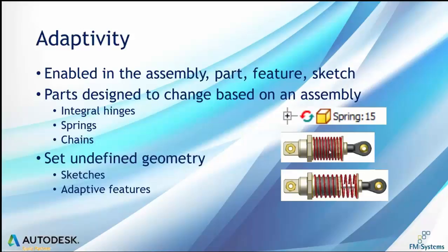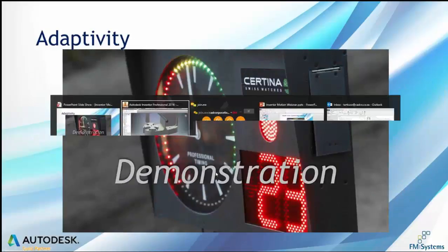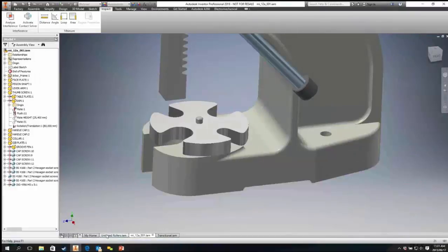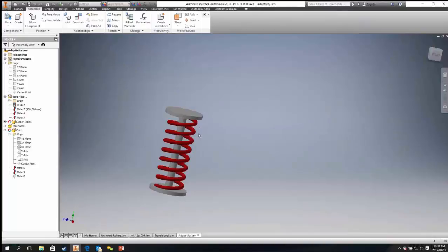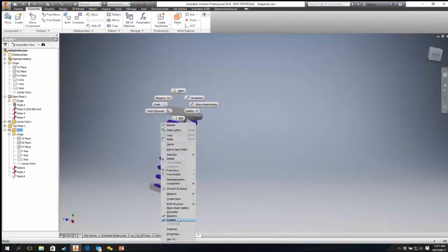But we also can use this information on different levels. I can override a value that I've specified as a dimensional value and make that value adaptive so that it can change freely based on constraint limits. Okay, so we'll look at that and see how we can actually use that. So let's really jump into an example. If I look at this over here. Now, in this case, let's say, for example, adaptivity was not on any of these components. Okay. So I take adaptivity off.